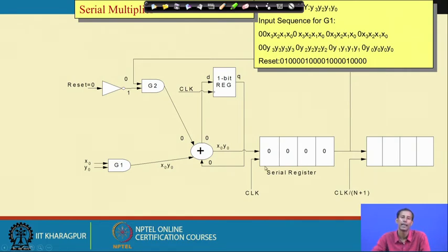After that, what I said is that there are different types of multiplication operation. The first thing is what we know initially: shift and then add. That is why this is the serial multiplication operation, the basic multiplication operation or multiplier architecture, not the algorithm, the technique which we learned during our school times.